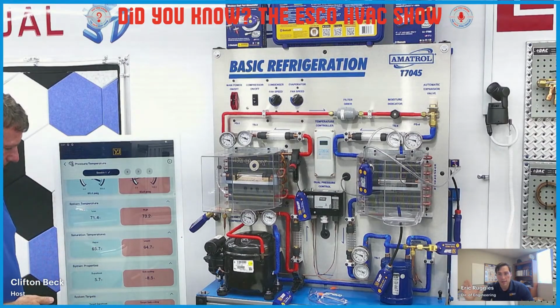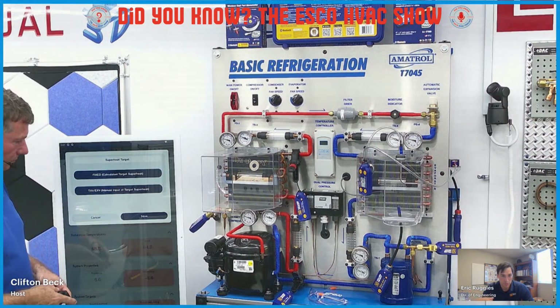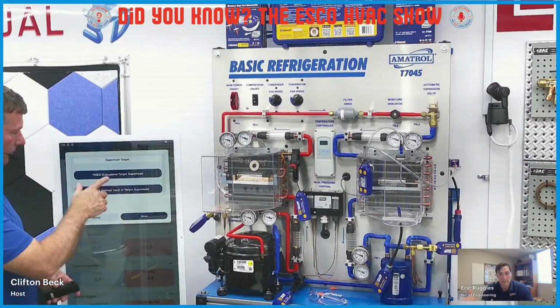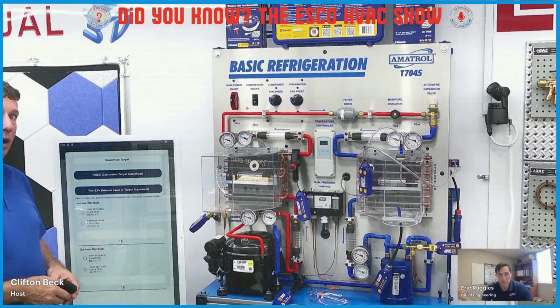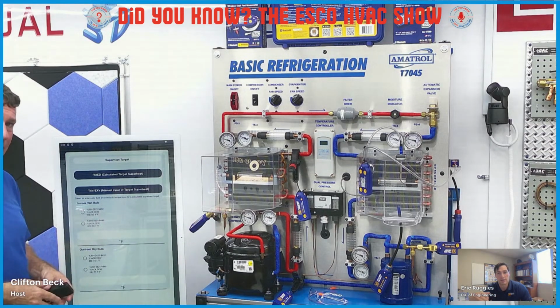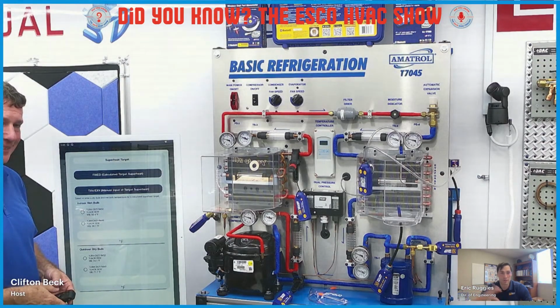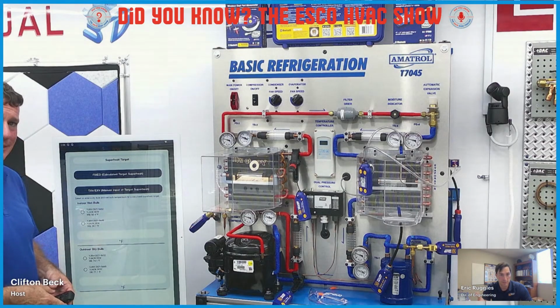Yep, so absolutely. You've got a nameplate of a system, or what you're typically doing for a type of product. On the superheat target, you can actually use an input, which is the bottom one, or you can use a fixed calculated superheat value. In that case, you can take the indoor wet bulb and outdoor dry bulb from your psychrometers. Yep. And then that will auto calculate. The nameplate is based on specific conditions, right? Yeah. But if it's an extreme condition, those superheat numbers are going to be off, right? So you want to use it for the actual conditions. You can do it calculated based on a fixed value.